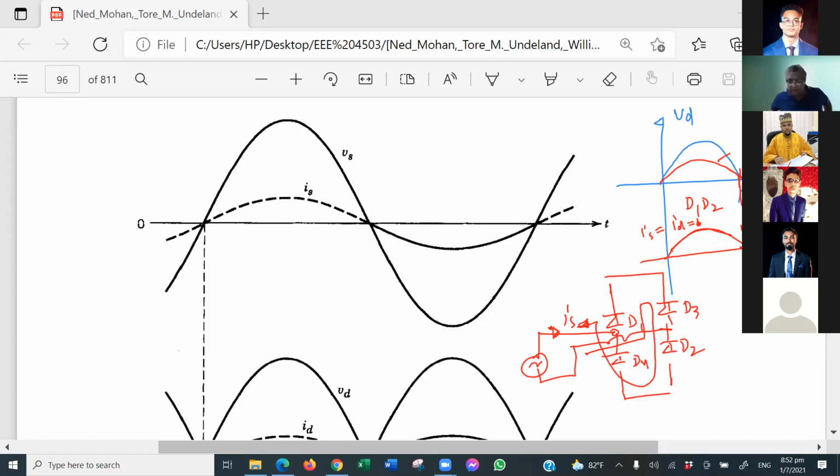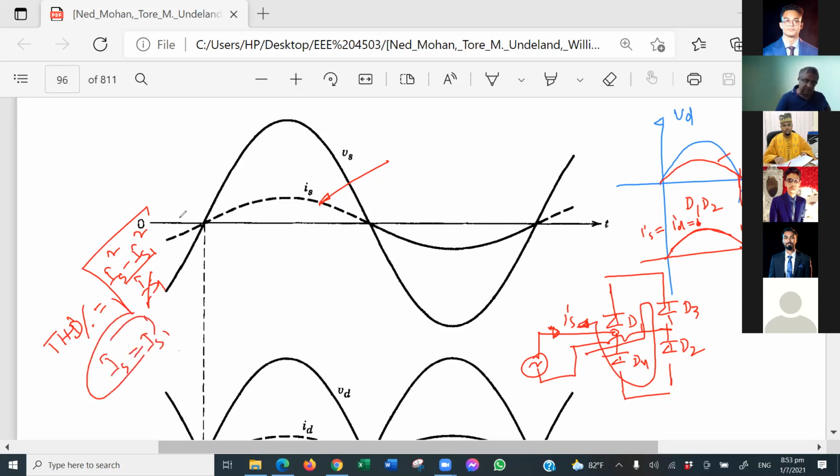Now my question to you as master's students: what will be the harmonics of your IS? Does it contain any second, third, fourth, fifth, or sixth harmonic? No, sir. It has the same frequency as the input voltage, right? Yes, sir. So total harmonic distortion, did I define it? Yes, sir, in the previous class. Okay, so look here, we don't have other harmonics, so actually IS equals IS1. So our total harmonic distortion is 0.